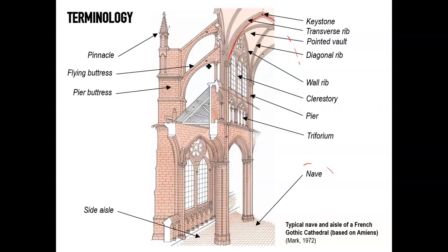On the outside, very often you'll find there's a system of buttresses that comes from the vault and then discharges some of the lateral loads of the vaults by using flying buttresses, which are spanning from the side walls of the church into some external buttresses, connecting the two, often with an angle, sometimes more pronounced than other times, sometimes with a segmental arch, sometimes with a quarter of a circular arch, sometimes in tiers, sometimes bifurcated, so there's many variations.